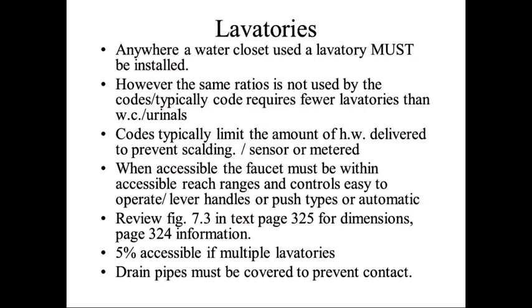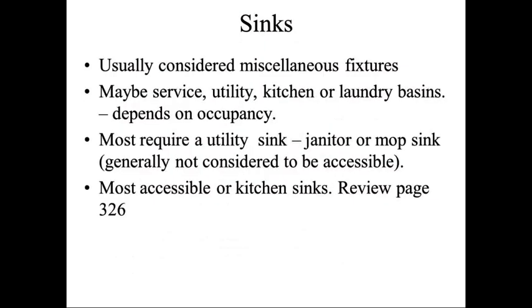5% of the lavatories have to be accessible, and the drain pipes below must be covered to prevent contact. Remember, it's usually open or they're covered underneath because you've got to get the wheelchair underneath the sink area.